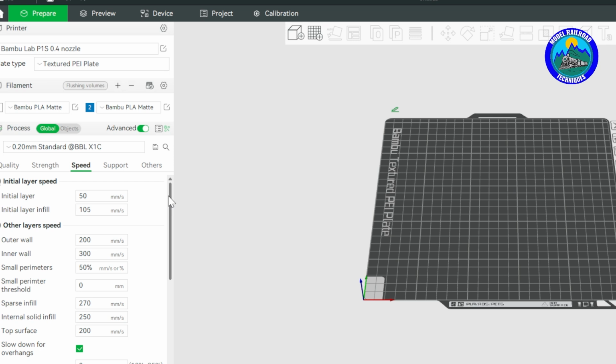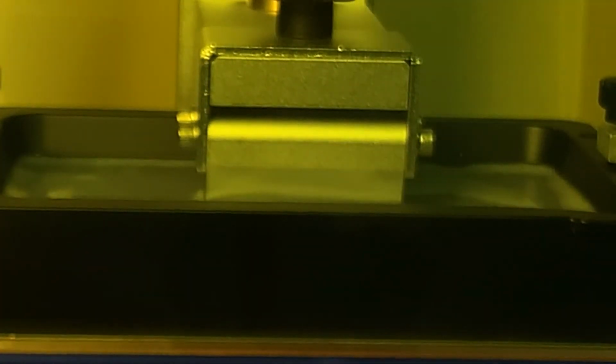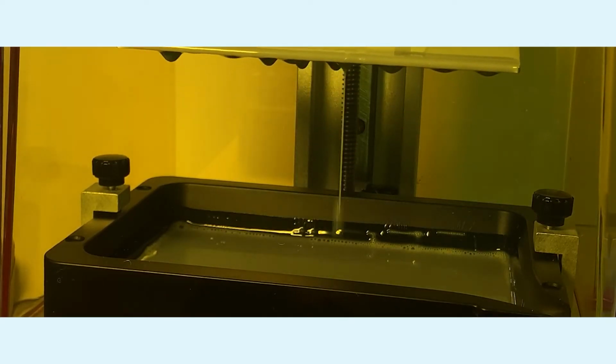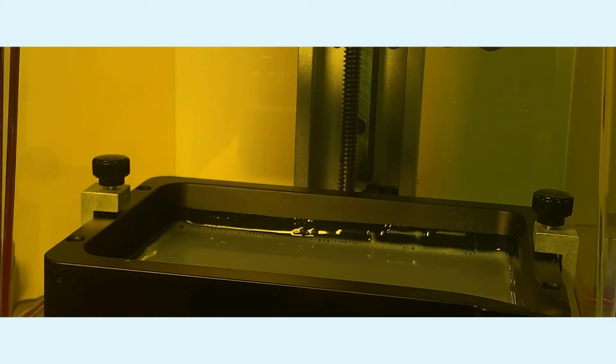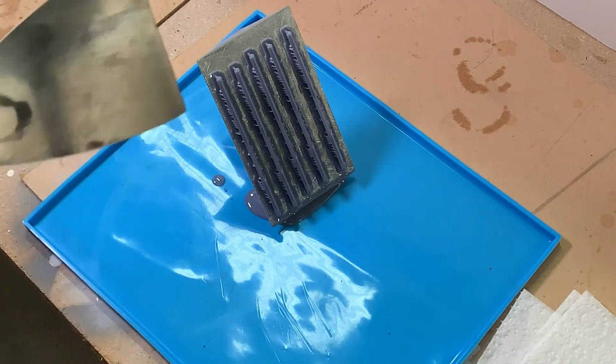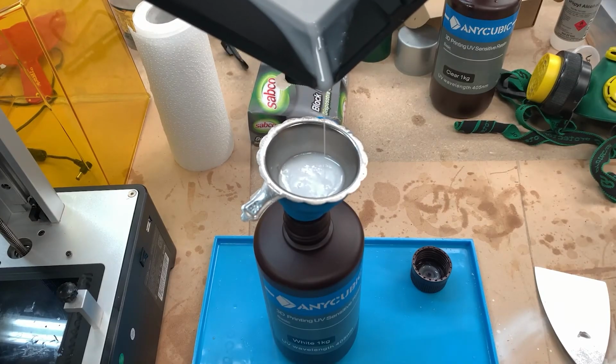But obviously the other one, if you want to get into it, is the resin style printers with the UV light that cures each layer. Also very, very good. However, what I like about the filament over the resin is there's no cleanup. The thing that I hate the most about resin is the stinky resin. And yes, I use some water-based resins, but they are still very, very toxic, and I always have glasses, gloves and respirators on because you just don't want to be breathing that stuff in.